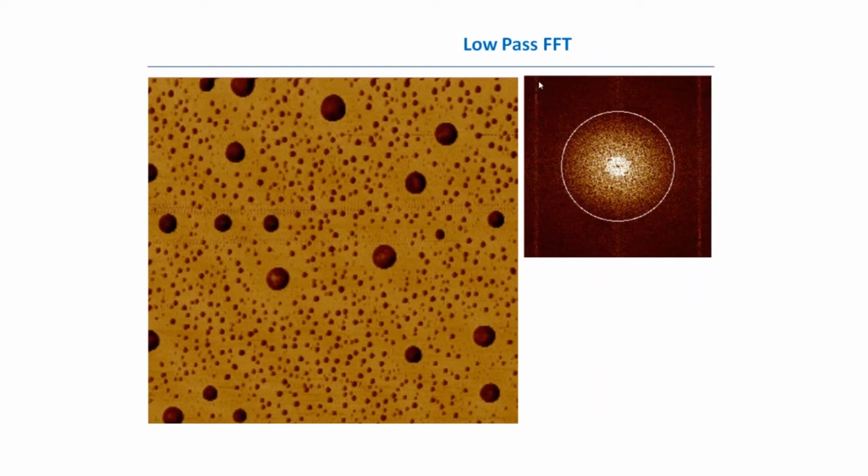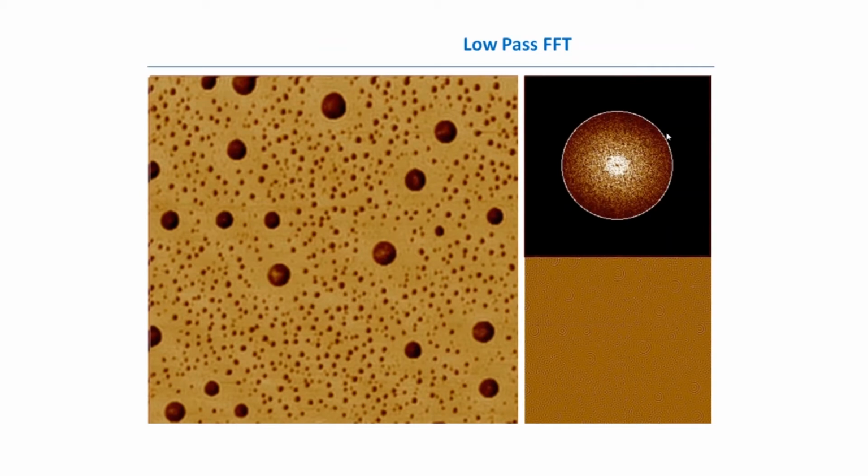And we also see some high frequencies which probably correspond to the noise. If we use band pass filtering, meaning that we delete everything outside of the chosen band, everything which has higher frequency or smaller wavelength than the chosen threshold, you'll see that this high frequency noise has gone.